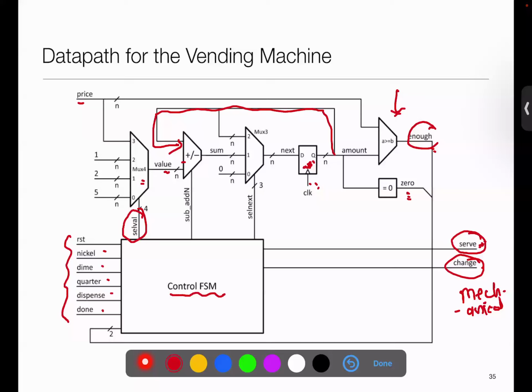If it was a car or a drone or whatnot, these are going to be coming from the sensors and the motors and all the things. So this is where either you are given these signals and then you just design for it, or more typically you are designing what the signals should be and what my finite sequential system should do, all of them together. So once we have all of this, then our task really boils down to writing a program on this control FSM. This is a little program, which is often referred to as microcode or firmware, all sorts of names given, or just hardwired logic, right?